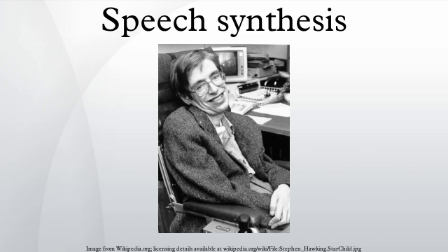Formant synthesizers are usually smaller programs than concatenative systems because they do not have a database of speech samples. They can therefore be used in embedded systems, where memory and microprocessor power are especially limited. Because formant-based systems have complete control of all aspects of the output speech, a wide variety of prosodies and intonations can be output, conveying not just questions and statements, but a variety of emotions and tones of voice.